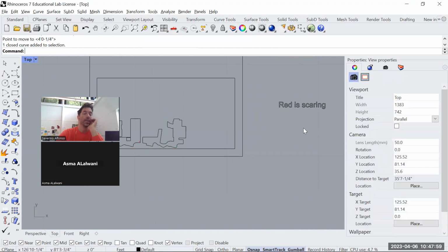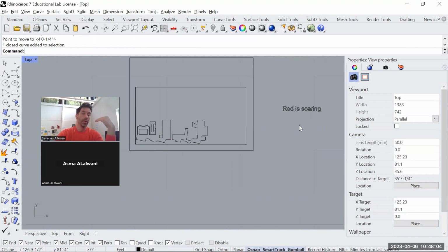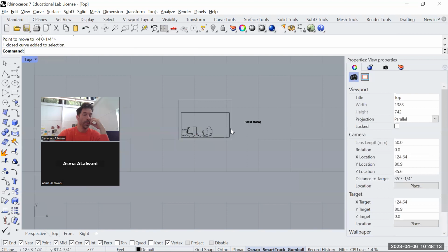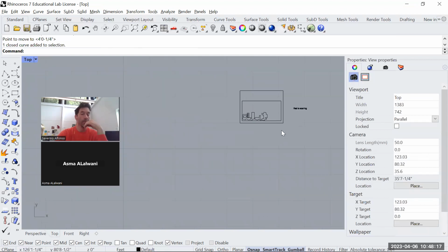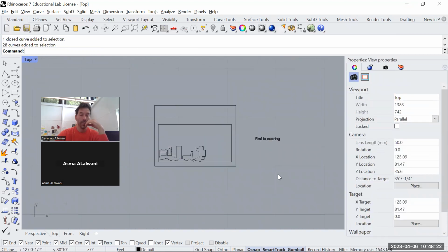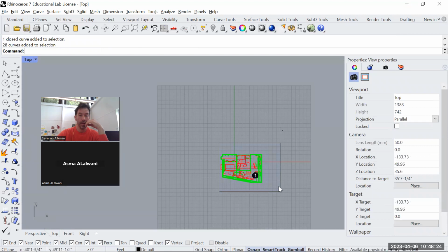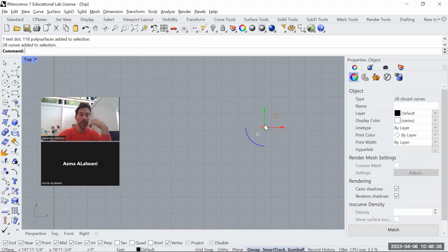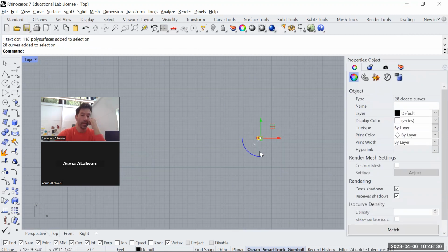You can say, this is my panel. You can say, this is the material I want. You need to bring the material, obviously, and you need to bring your vector file on a flash drive. And you can just leave the file for them to do it, or stay there? They do it, and the comments are helpful for that. If it's your first time, you can talk to them to make sure things are going correctly. Now look at what I have here. I have all this stuff, and then I have obviously this stuff. I would recommend you save as and make sure only these elements are in the flash drive.